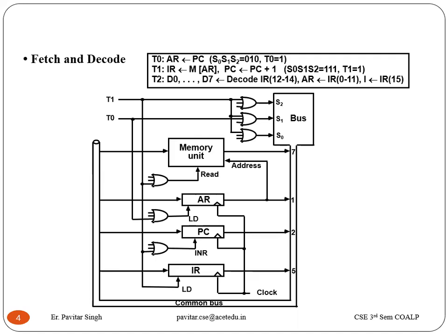The instruction at the 0th location has its address given to AR and that instruction is transferred to the IR. After that, the first location instruction will be read out, and for this you need to increment the value of the program counter, right?